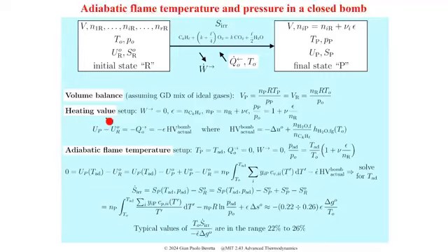So for example, for the heating value, you could measure a heating value at constant volume. You would have no work exchange, and you will have a heat exchange enough to bring your products down to the environmental temperature. But you have to accept that since it's a closed volume setup, the final pressure will not go down to atmospheric. And it will be a pressure P that, determined by the ideal gas law, is determined by this thing.